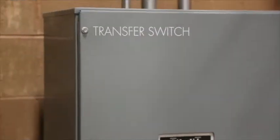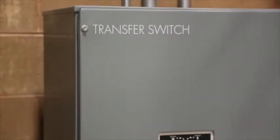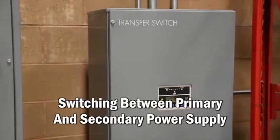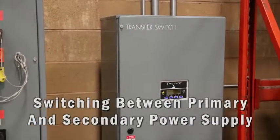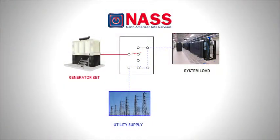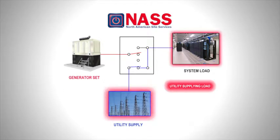Many standby systems are there to provide backup power to critical life and/or economic load, such as hospitals and telecommunication stations. Typically, an automatic transfer switch, most frequently called an ATS, is used to transfer the load between the primary power source and the standby generator set.